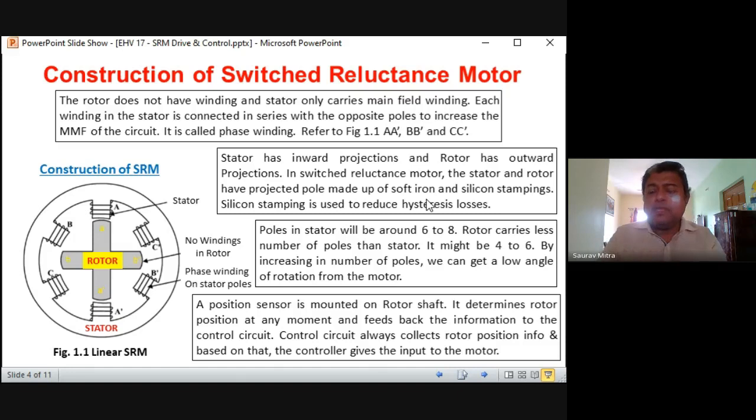The second input was the current stator current that is given. What is the present stator current which is rotating the BLDC motor? For all these three phases, how much current is being given to the stator coil, and how much power input we are giving to the BLDC, that information was coming to the DSP. And the third thing was another input feedback, which was the rotor position at present.